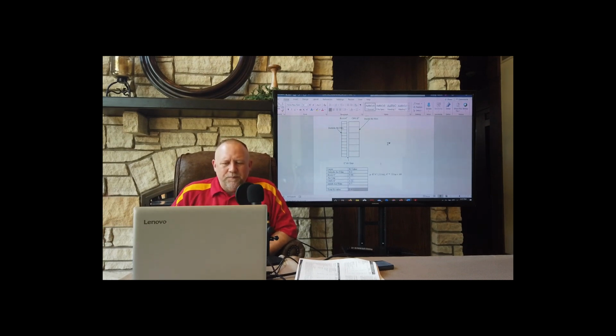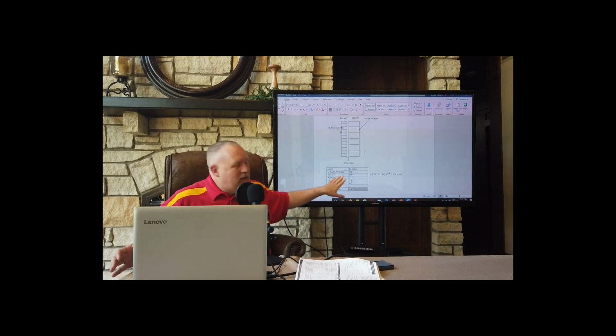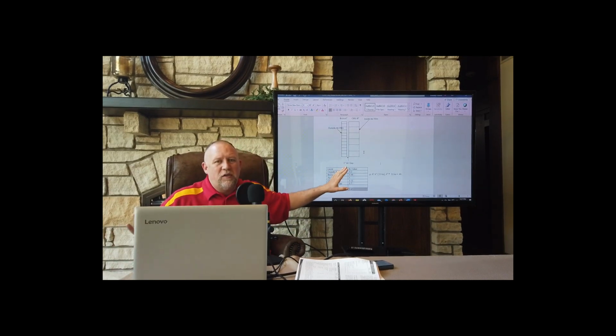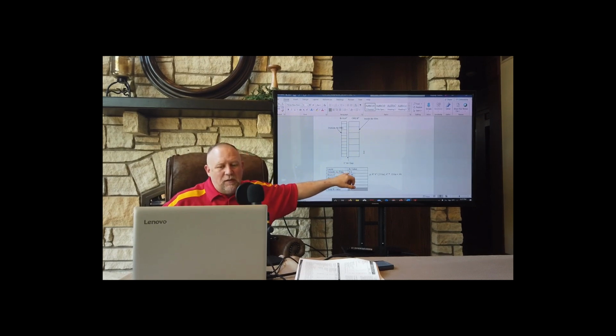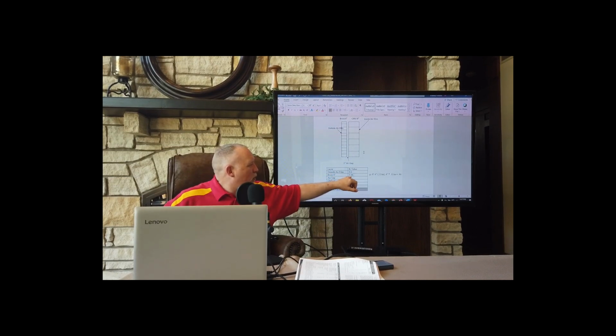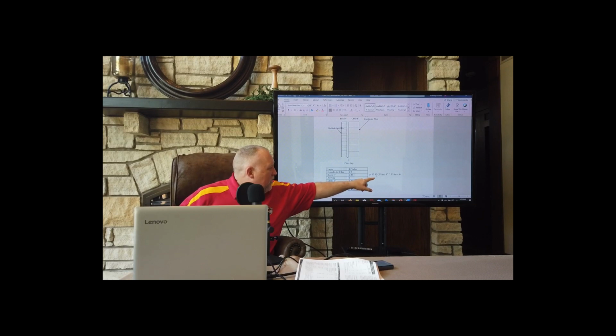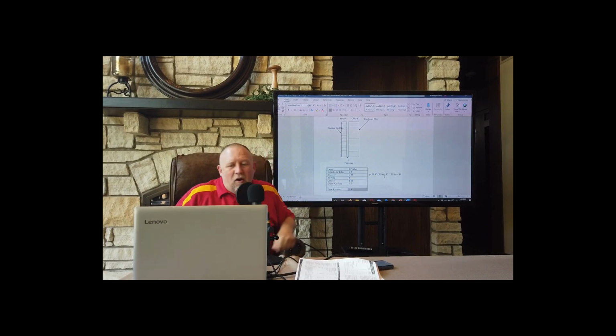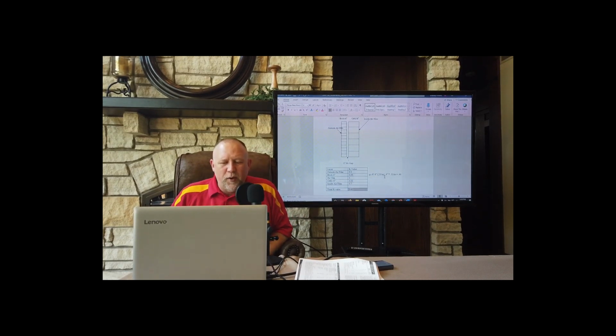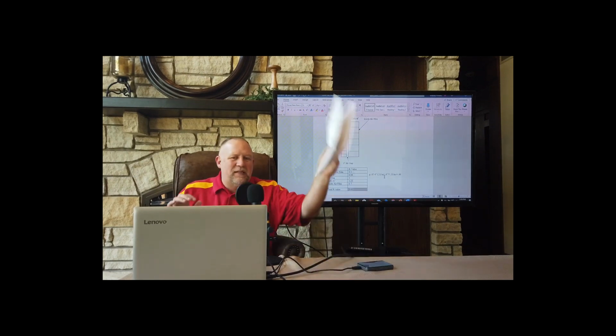And notice, as we add up these values, this is how I want you to do it for your homework and for the final project. Go from outside to inside and just add them up. List them. I want to see this. So the outside air film has a resistance of 0.2. The brick itself has an R value of 0.44. You take that R value of 0.11 per inch that we looked up in this table.